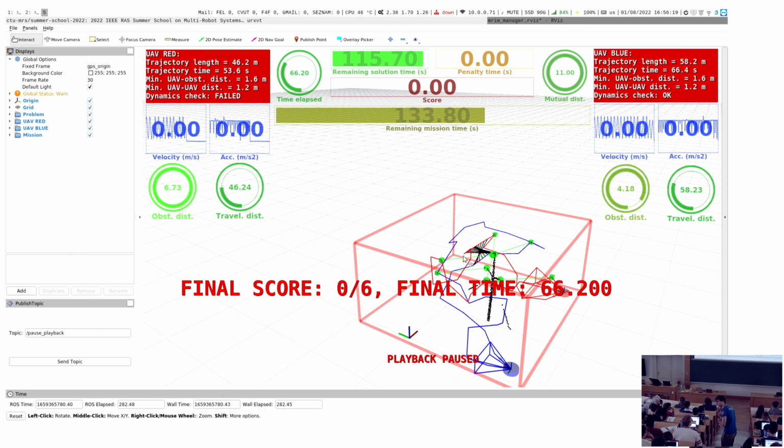Sorry, and just to continue that line of questioning, is it Arduino Pilot? Is it PX4 Arduino Pilot? We use PX4, yeah. And so the only way to communicate with that low-level system is via... it's not possible to, let's say, design a high-level controller that only deals with the waypoints. We have to communicate using thrust and attitude or position values.